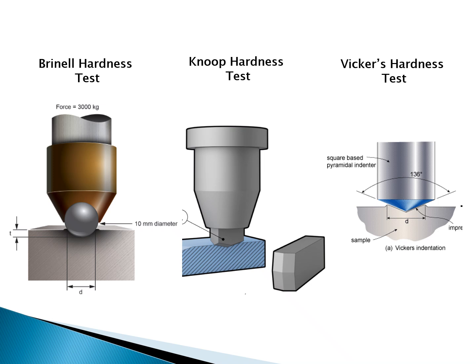Hardness is generally tested using various types of indenters. Some indenters can be a round steel ball with various diameters, as used in Brinell hardness. Usually a steel ball of 10 mm diameter is used. The Knoop hardness uses a pyramidal shaped indenter, and the Vickers hardness uses a 136-degree pyramidal indenter.